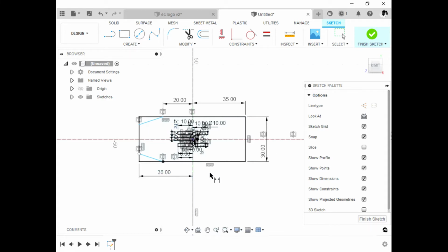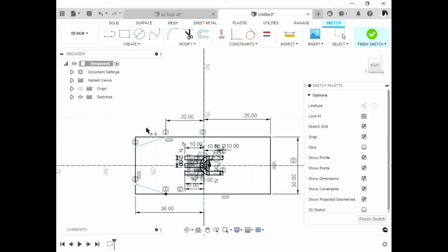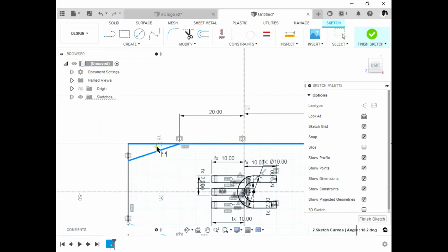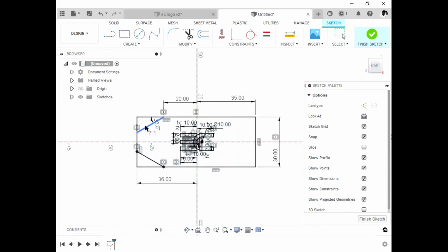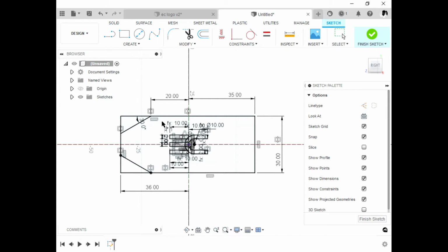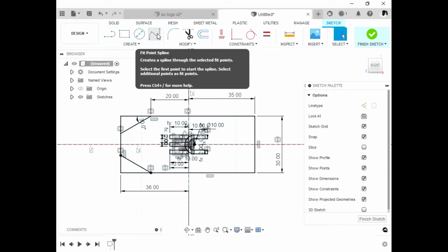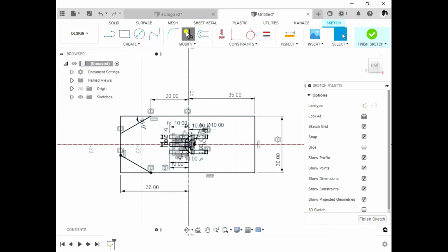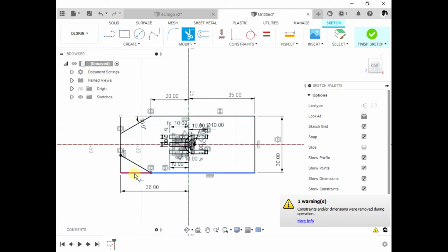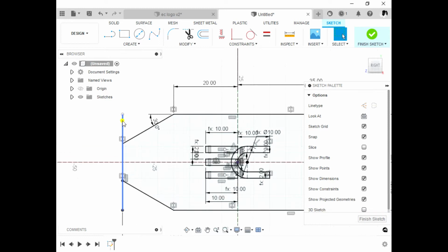So I can see there is one area where the constraint is not yet added, the area where the line is green. Let's do 30. 30 looks good. Now we can select our trimming tool to trim these unwanted parts. I don't want that. Don't want this. I can make this a construction line. Yeah, exactly. So this looks good. I just joined that figure there.